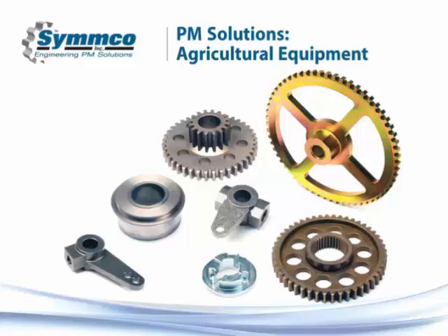Perpendicularity is also something that can be easily addressed with a very, very slight machining, where we would push it up against whatever face was our major datum and take a very slight cut on the board to drive perpendicularity to a face. So there are ways, especially for perpendicularity or a very high flatness requirement, that if we can't achieve it using common sintering furniture, we do a very slight machining process to drive to a tighter tolerance.